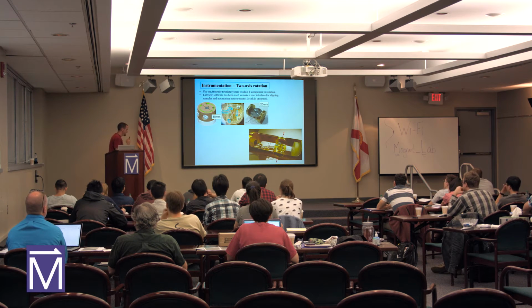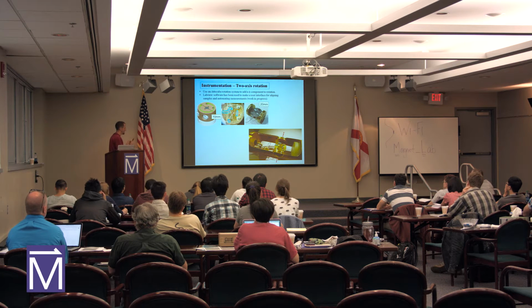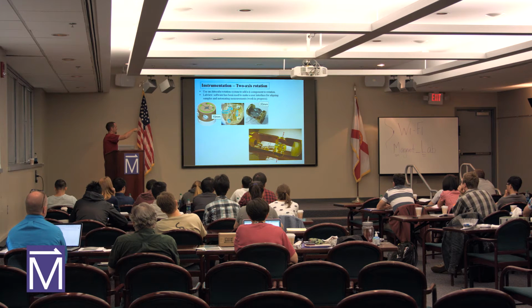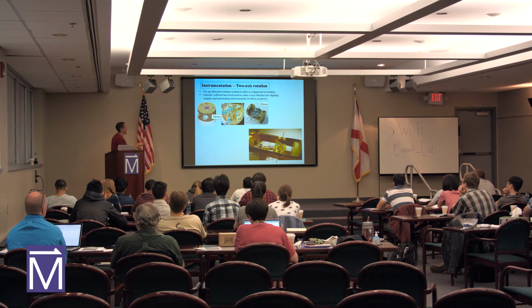So how might you actually physically do a measurement like this? We're talking about rotating something in theta and phi. One way you might do this is with a two-axis rotator. What that means is we have a piezo rotator. This rotator moves around in a circle, like a CD or DVD player, when you send voltage pulses to some little piezo elements in the base of it. If you put a sample platform on top, there are all these little copper tabs that we have tiny samples attached to, with little wires going to them, and those wires go through the center axis of the piezo rotator.